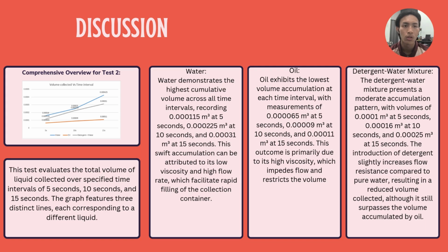First one, water. Water demonstrates the highest cumulative volume across all intervals, recording 0.000115 meter cube at 5 seconds, 0.000225 meter cube at 10 seconds, and 0.00031 meter cube at 15 seconds. This swift accumulation can be attributed to its low viscosity and high flow rate, which facilitate rapid filling of the collection container. Next one is oil.